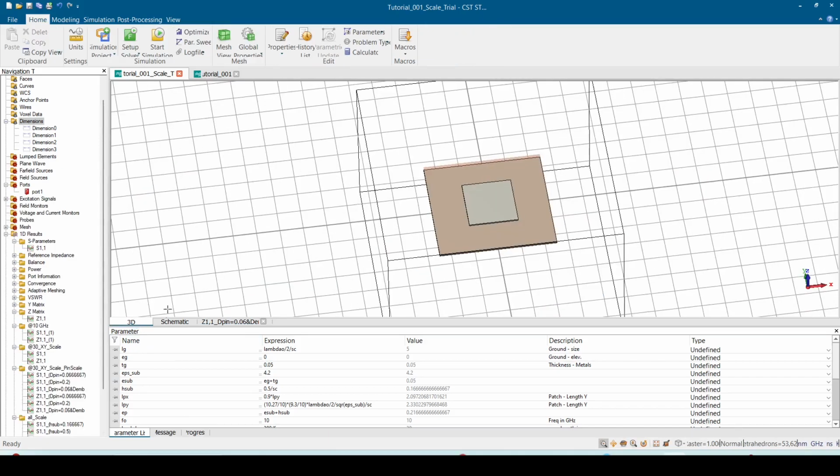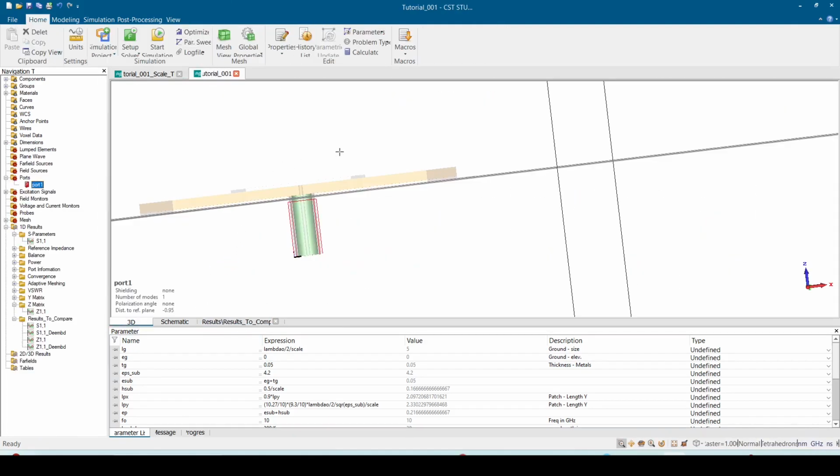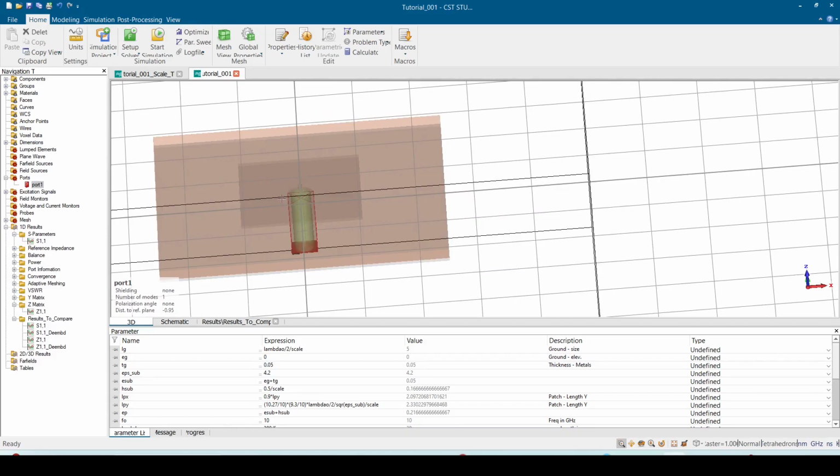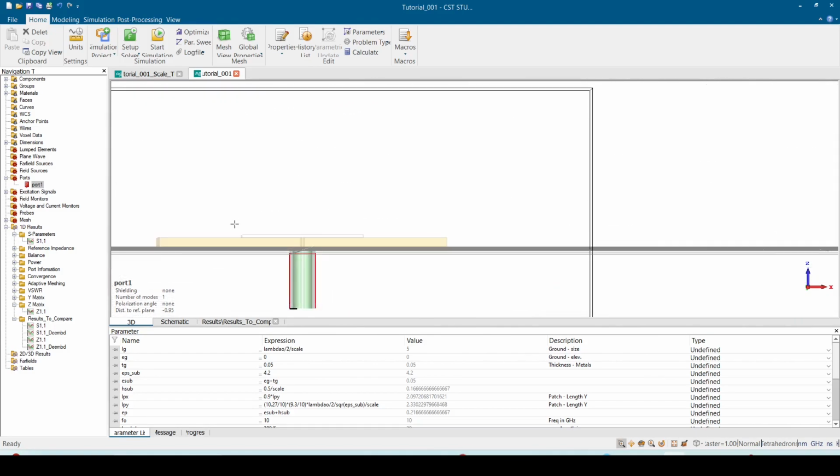So the second advice is that you had better de-embed and be sure that you only handle the patch antenna impedance, right? So these are the two things, and scaling the height as well, because everything is described by the image theory.